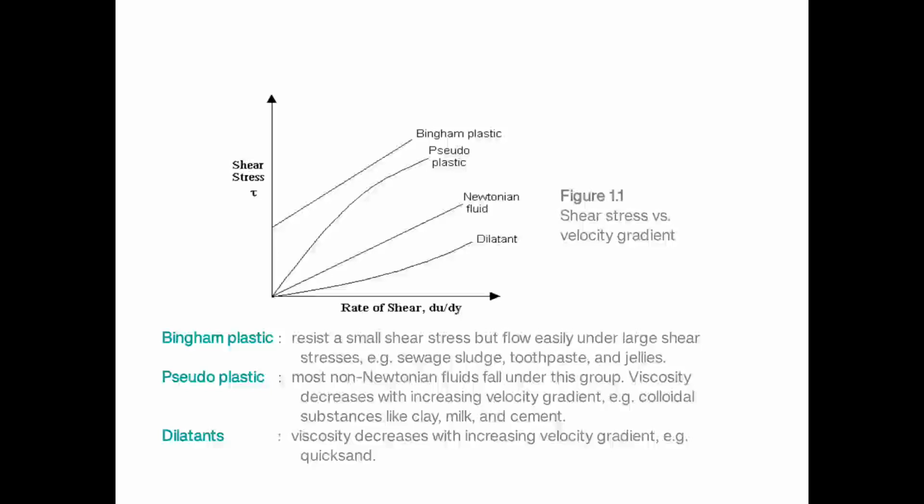For large shear stresses, it almost becomes constant. If you measure the slope at various points along the curve, viscosity decreases with increasing velocity gradient or shear stress.